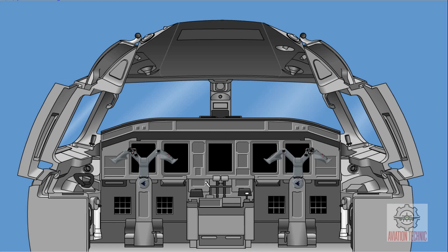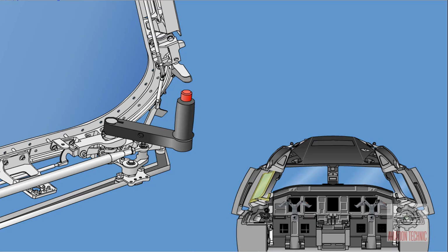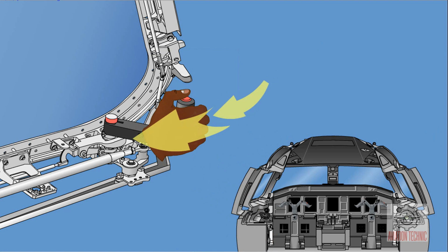The crew emergency windows are located in the cockpit on the left and right-hand sides. When closed, they are pushed against the window frame by an over-center mechanism, and held in position by a locking mechanism. The windows are opened manually. They have a locking mechanism that is released by pressing the button located on the top of the handle. As the window is unlocked, the handle must be pulled backward in order to actuate the roller's latching mechanism, sliding the window inside and backward along the tracks.